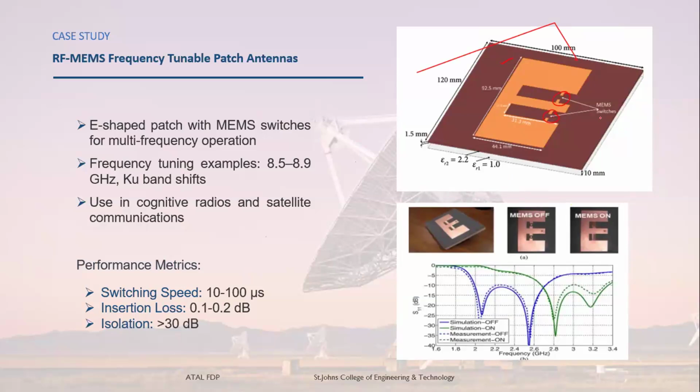When the diode is in off state, the antenna operates at, look at this. First of all, you should understand what happens when the switch is on, the current path is different. Current flows in a longer path, operates at low frequency. Current flows a shorter distance, the antenna operates at a high frequency.